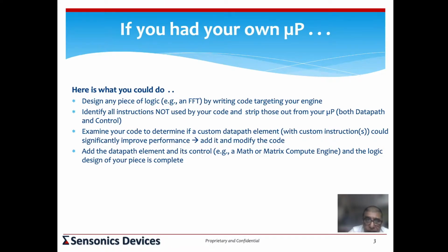And then once you've implemented it, you could take a look at all the instructions that you have not used from that engine, from the RISC-V, and delete those instructions, the corresponding data path elements, the corresponding control elements. And now you have already added, if necessary, some additional logic. And then this piece becomes a customized piece, very efficient, and based out of logic that you have designed, the completion of which you have done through your RISC-V design, and therefore the amount of effort that it takes you to build this is orders of magnitude less than if you had to build an FFT engine from start.